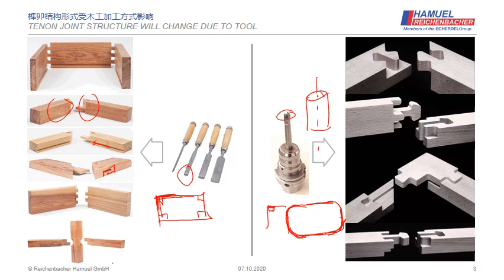So in this case, it's necessary that the designers optimize the designs, with a radius on each corner, and this will be much easier for the CNC machines and for these modern tools. So I mean, this is also a case where the manufacturing technology changed the design.